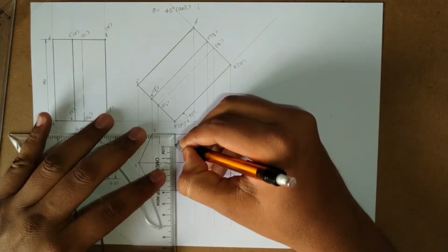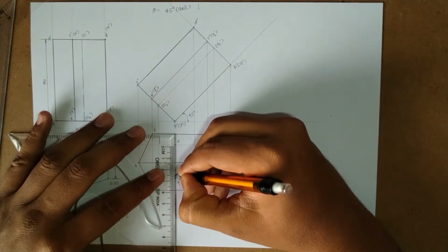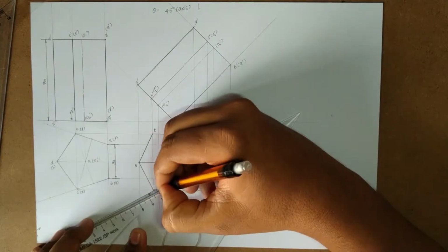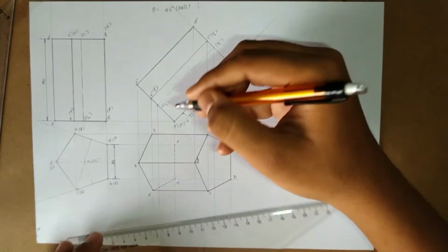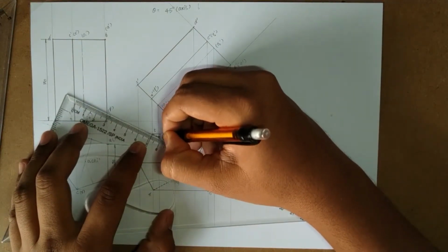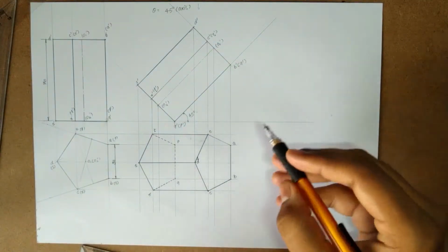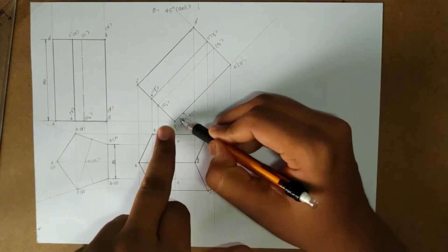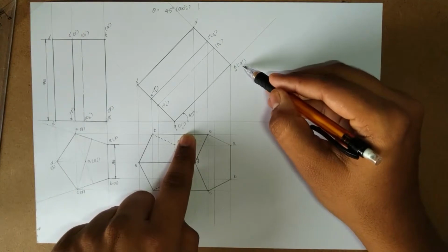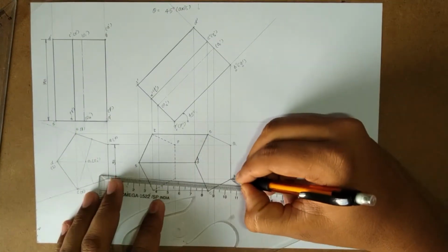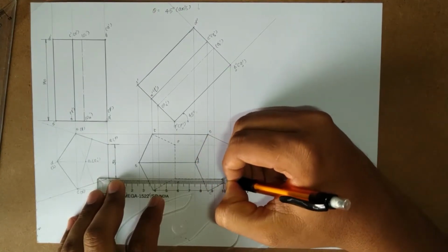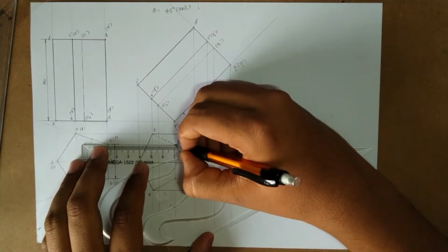So the P to Q connection is invisible, so we will represent it with a hidden line. The Q to R connection is invisible. R to S, S to T, T to P connection, which is once again invisible. Now the remaining connection from P point and from Q point. Q point will connect to B dash point, that is, Q will be connected with B, and P dash is a hidden one, so it will be connected with A dash, which is the hidden one over here. So yes, this line will also be hidden. This will be the hidden line, and this will also be the hidden line.